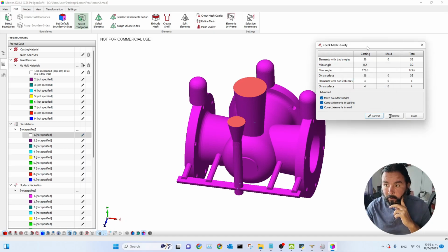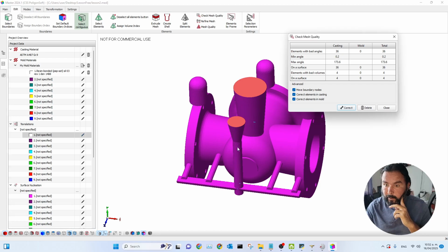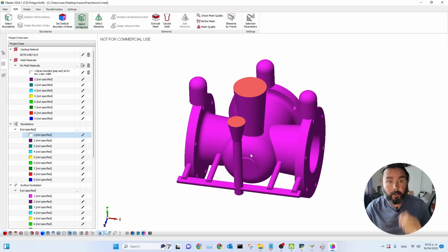The program couldn't correct the triangles. It seems there's some kind of geometry limiting them. In that case, it's okay. We simply delete all the triangles we don't like. Done. The triangles were deleted. We can see we have no more problems in our model.